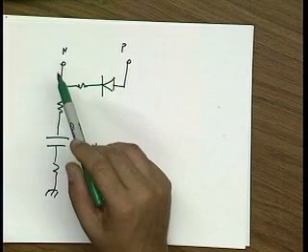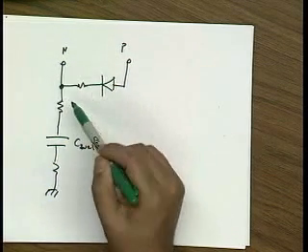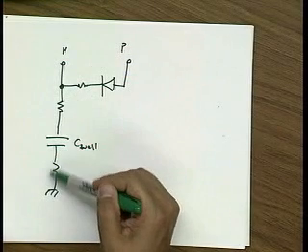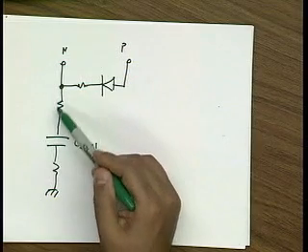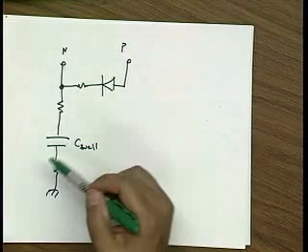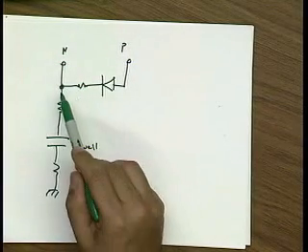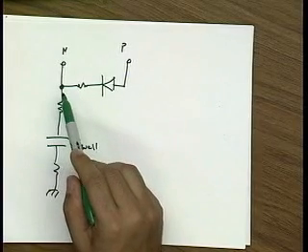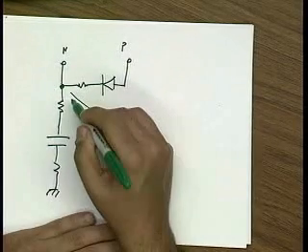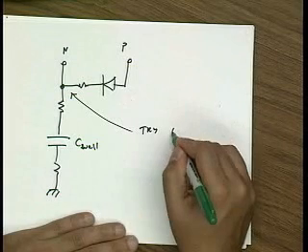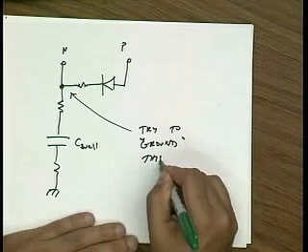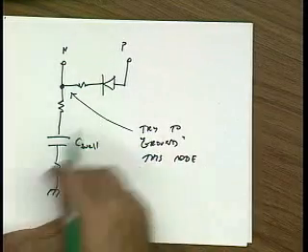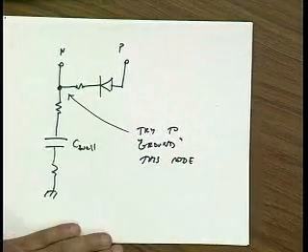Because if a voltage swings on this node, then current will go into this branch here, and basically you'll get loss through this resistor and this resistor. And so that will de-Q the tank. So really I would like to ground this node. In other words, I'd like to choose an oscillator topology where this node doesn't move.